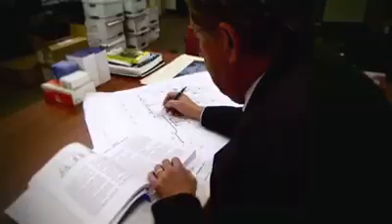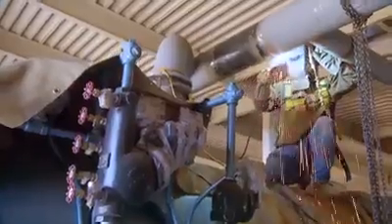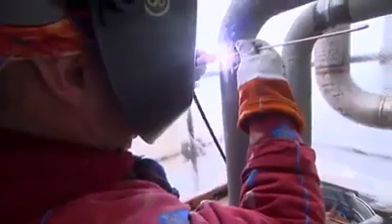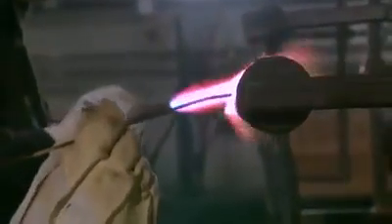ncpwb.org. While the engineer is responsible for material selection and design, the contractor is responsible for installing the piping following the specified B31 code section and the engineer's drawings and specifications. This includes being sure that the materials that the engineer specified are the materials that are installed, that the welders and brazers who will do the work have been properly qualified, and that those individuals are following properly written and qualified procedures when welding and brazing piping.